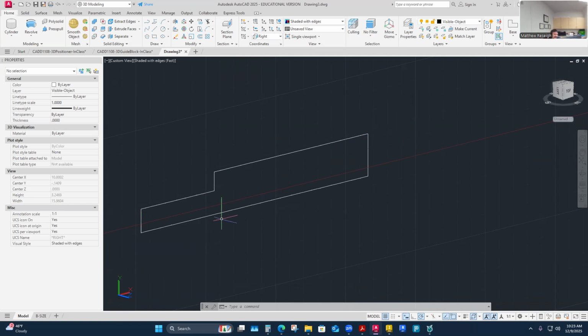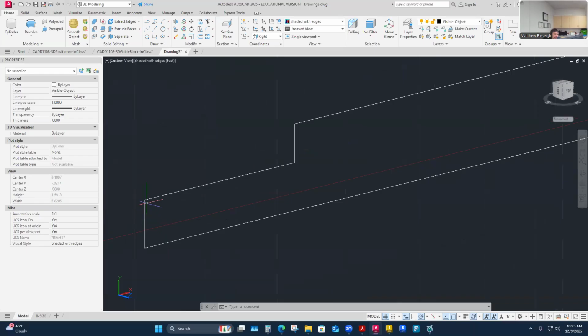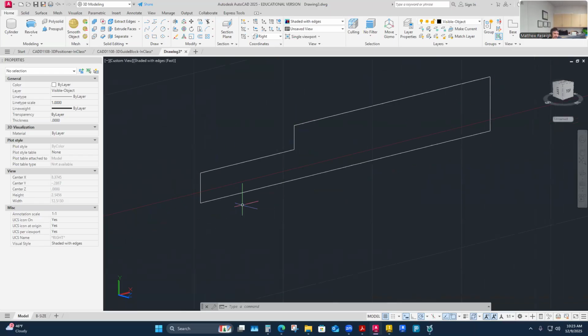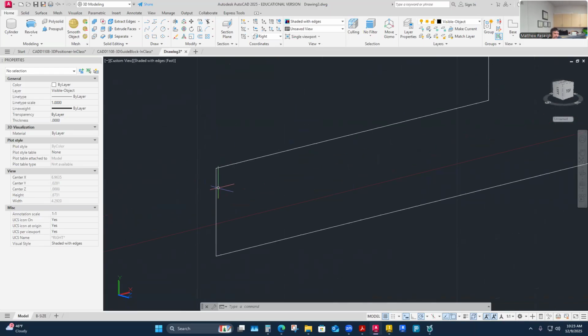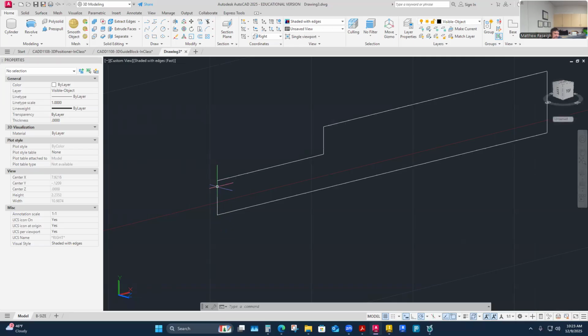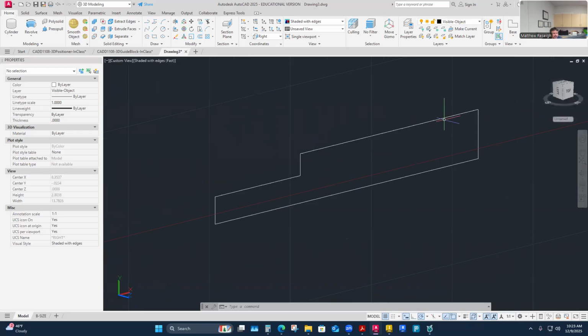The last thing I want to add is this: all my corners are square here, right? Right here, this one, I didn't dimension that. I just targeted this point, and then I came back and used my polar tracking, my object snap tracking, to locate it. Because I'm snapping it into that grid that's nice and square, I'm able to use those tracking lines to locate that.